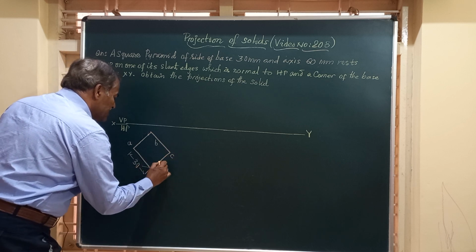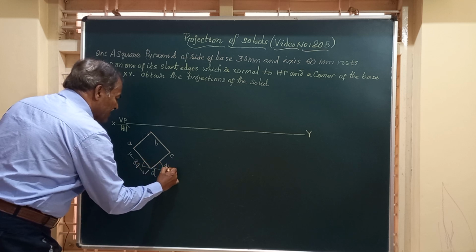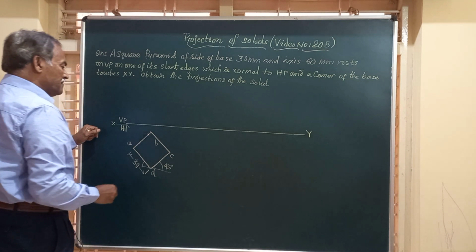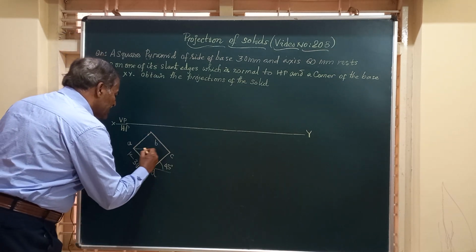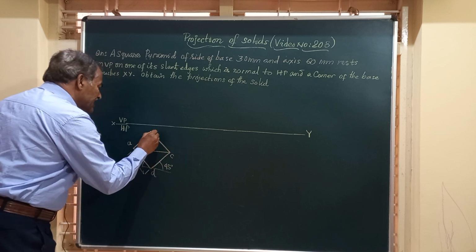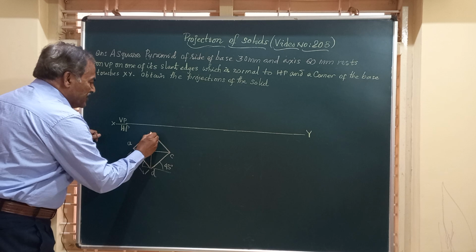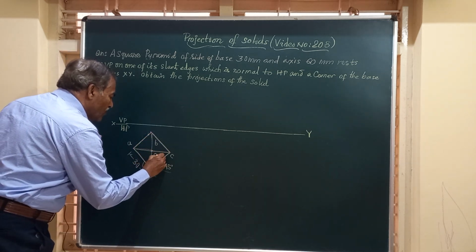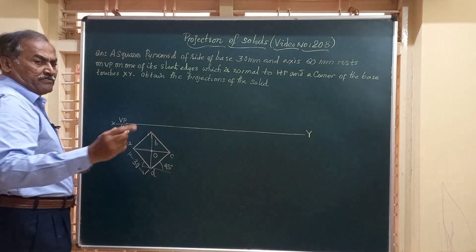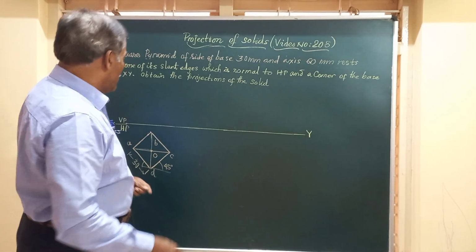And all these edges are equally inclined, so at an angle of 45 degrees to the horizontal. Friends, obtain the center of this by drawing horizontal and vertical lines through these corners A and B. Friends, these meet at a point. This is the vertex O of the solid. The tip of the solid is called the vertex. This is the vertex you have got.